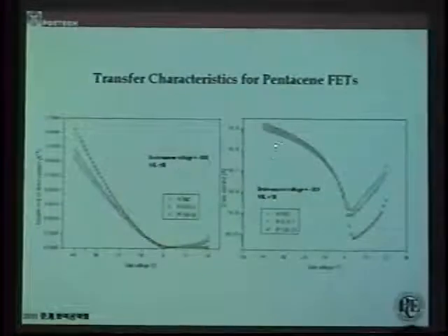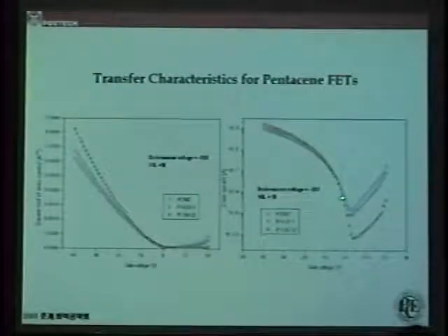This is a typical transfer curve, IV curve, showing that the red color is the lowest surface energy one. So this is the homopolyimide. The characteristic is much improved by reducing the surface energy of the dielectric layer. The mobility is the slope of this, and the highest mobility is obtained with the lowest surface energy.